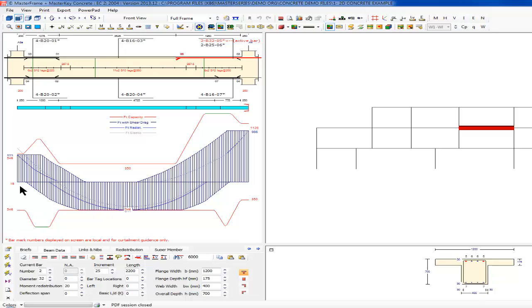So now we've gone to 20%. We're pushing the envelope here. We're right on the money. The sagging moment has physically now started to drop, but in this case we've got away with it. In other cases you might say, no, we have to go back up and put in the B20s. So you can see it's very, very editable, very, very flexible and controllable,